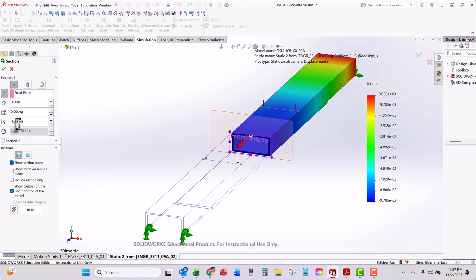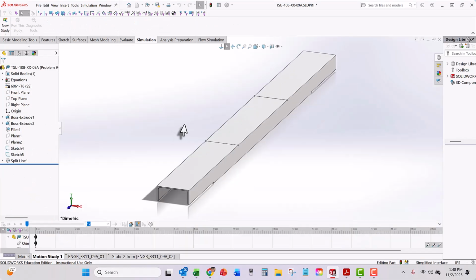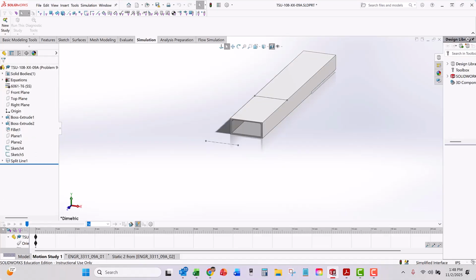and make sure my I values matched. Reset that. Go make sure my I values match. My moment of inertia matches what I had on my hand calculation. So I'm going to go grab this front plane again. Back in the model here, cross section, and I'm looking at my hand calculations over here. What did I use for I? Where is it? I used 4.66 for IXX.